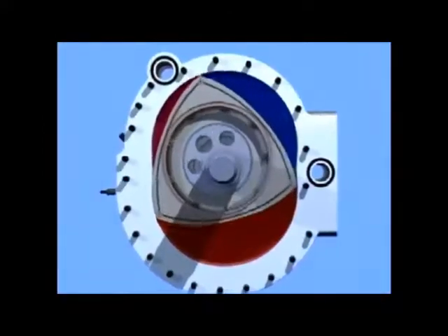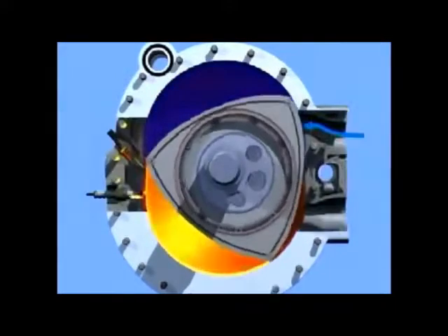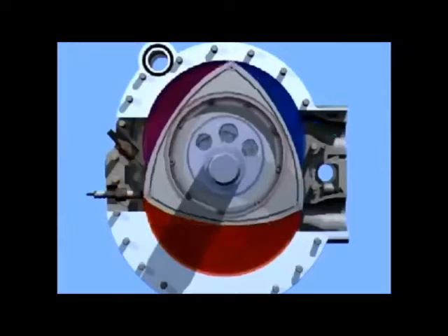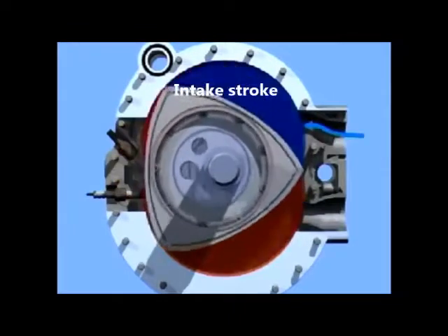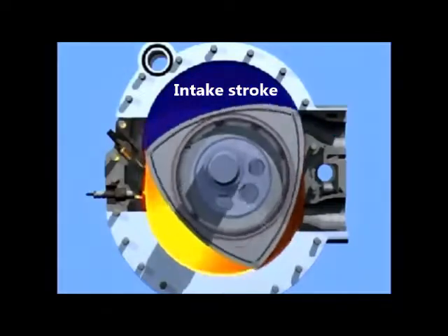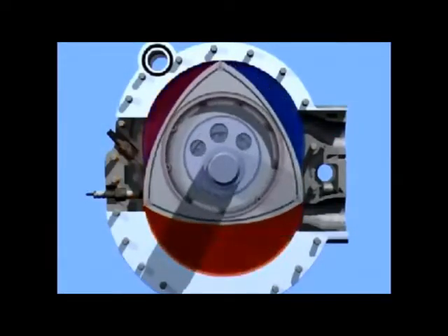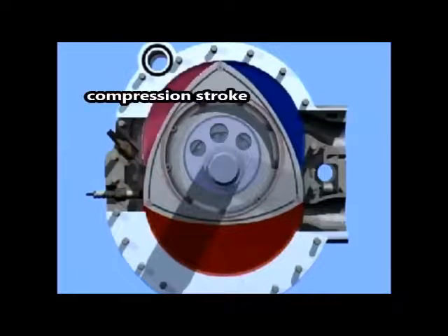These function the same as those in a 4-stroke piston engine. To name the 4 strokes, first, the intake stroke, where the intake air is allowed into the combustion chamber through the intake port. Secondly, the compression stroke, where the intake air is compressed by the changing volume of the chamber.